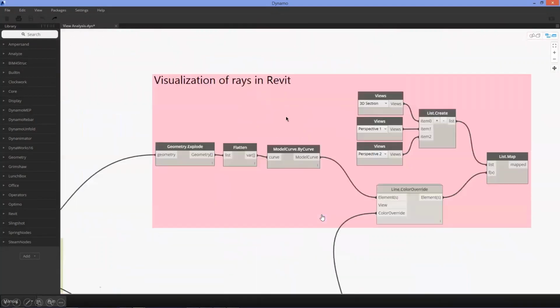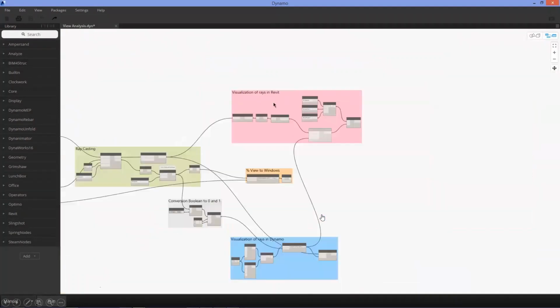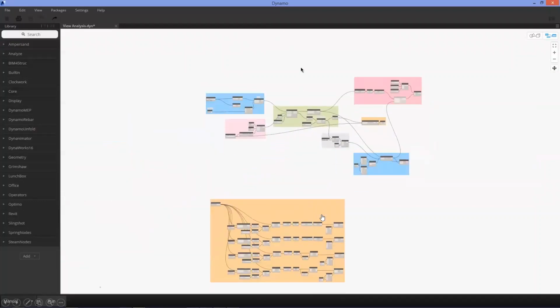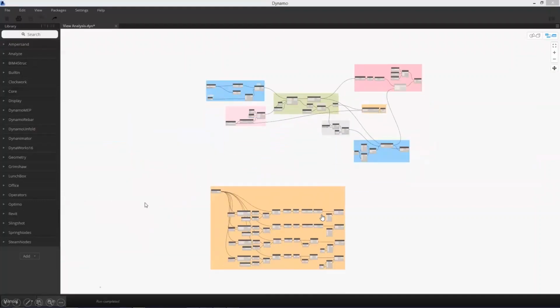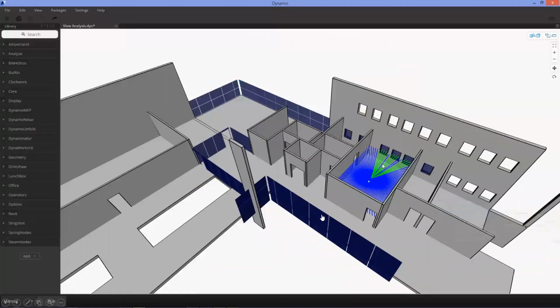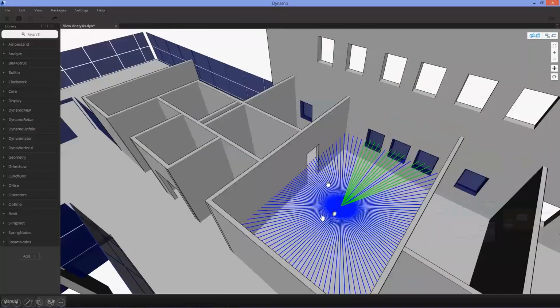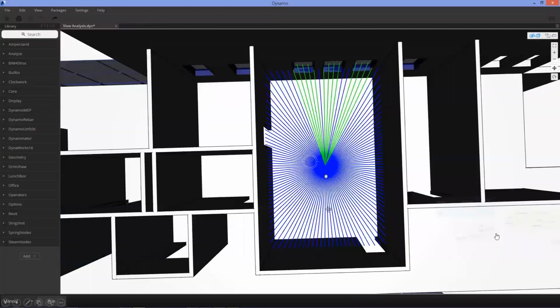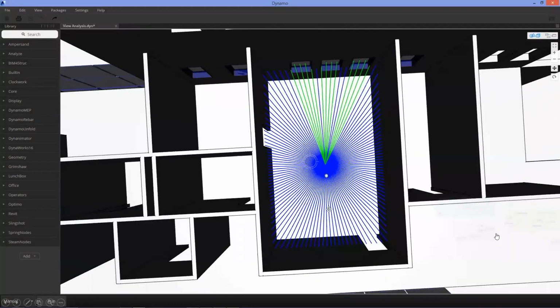You can change what the ratio or percentage standard needs to be for a particular building room or a particular building use as well. If it's residential, if it's apartments, or if it's commercial use, office use as well, you may have different standards. Or if you've got an existing building, you can see from that point, they can't see very much daylight, but Dynamo has calculated it for them in its entirety for that particular room.